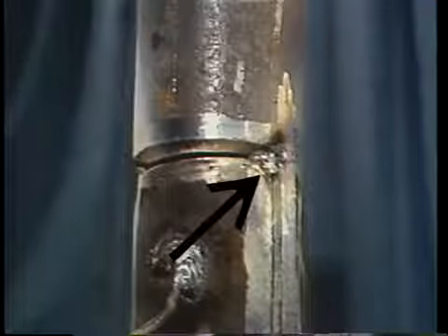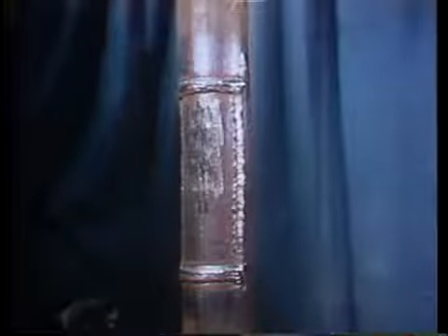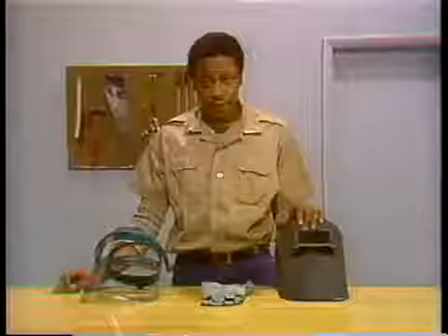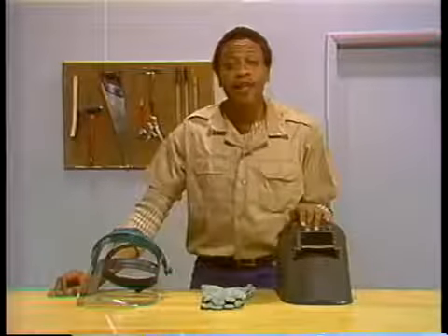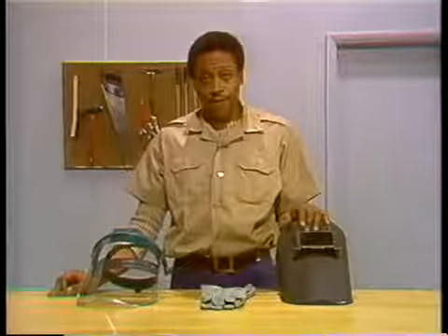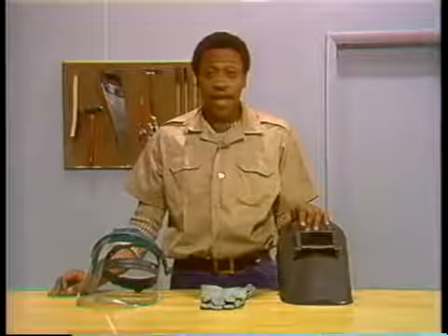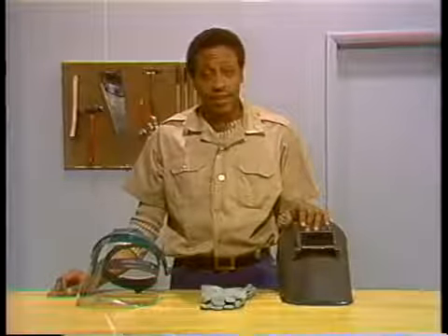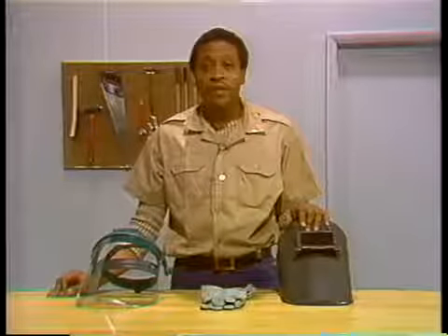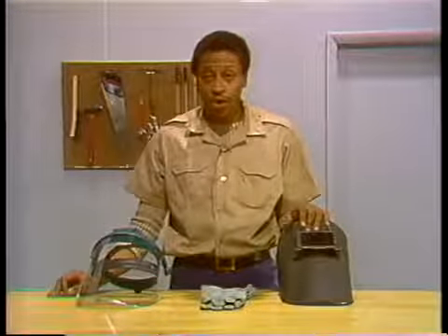Once the replacement patch is tacked, the final welds can be made. This welding job can only be done by a certified welder. Once the welding is finished, the window repair is complete. Whenever window repairs are done, it's a good idea to hydrostatically test the boiler. Generally, a hydrostatic test should be done after fixing any failure that has caused leaks in the boiler. The repair area should be inspected during the hydro to make sure it doesn't leak.